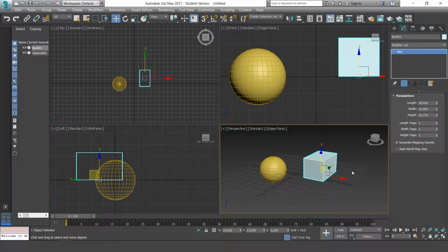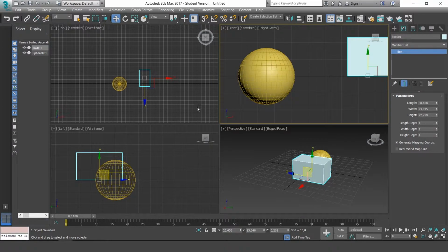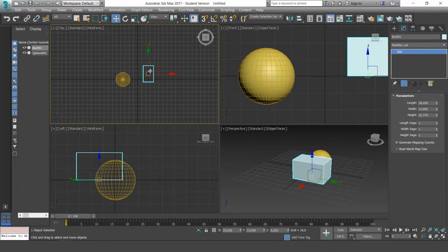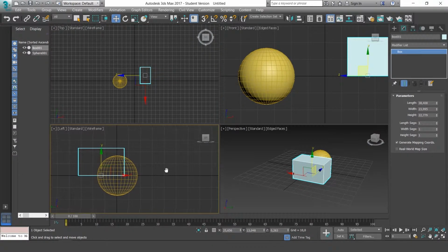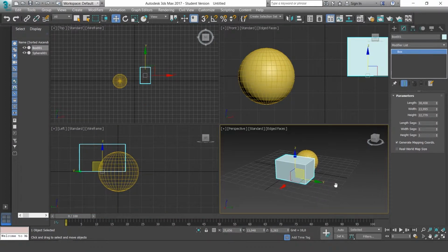You need to bear in mind that the axis on the pivot depends on the view in which we are working. You shouldn't assume that the Z-axis will be the height in the perspective view of front and top. As you can see here, the axis that corresponds to the height in this perspective is Y. Depending on the view, the pivot will act one way or another, and we need to pay attention to this.